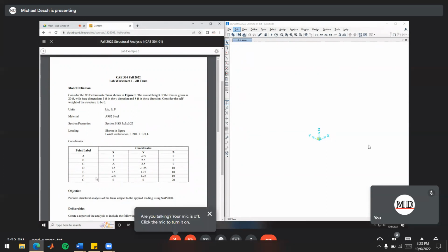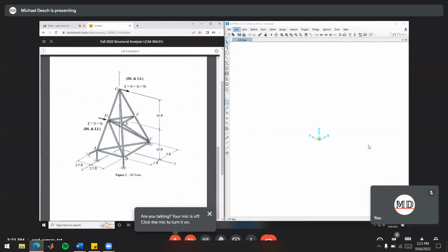However, when we have a structure like this, it's going to be kind of hard to go and draw all these elements all over the place unless we have some nodes to snap to. And we can do that by creating a big old complicated grid that would have a snap point at each of these nodes right here. But when we have large structures like this, that can get kind of messy, especially when stuff isn't spaced evenly. So I'll show you how we can insert nodes in arbitrary positions in 3D space to model this a lot more cleanly.